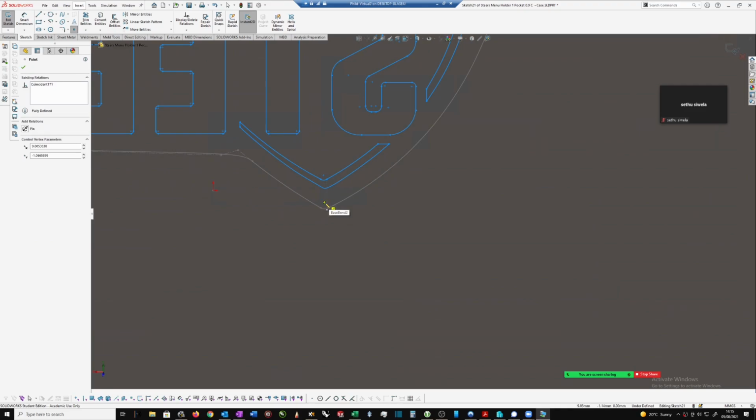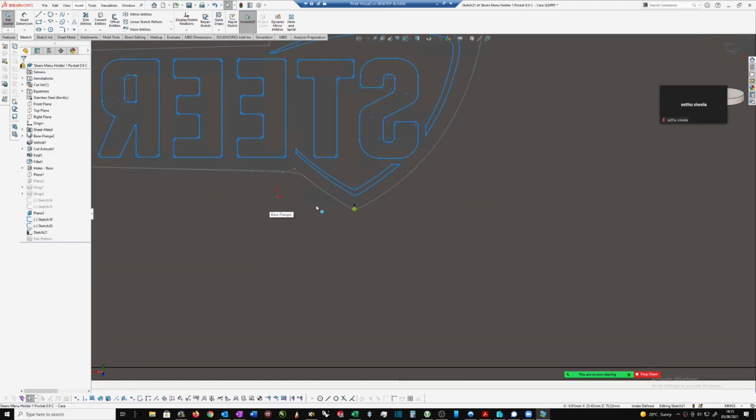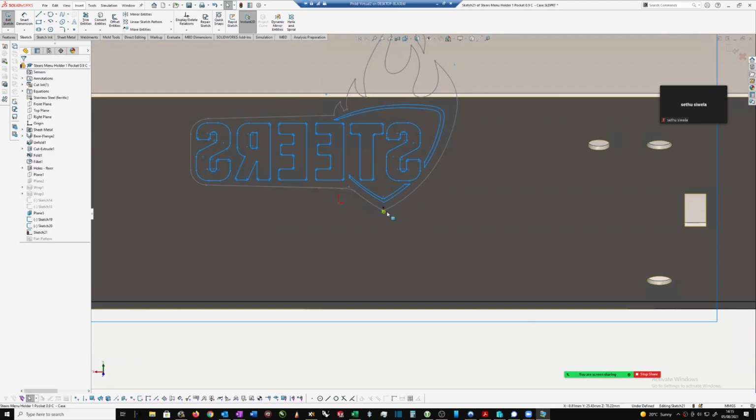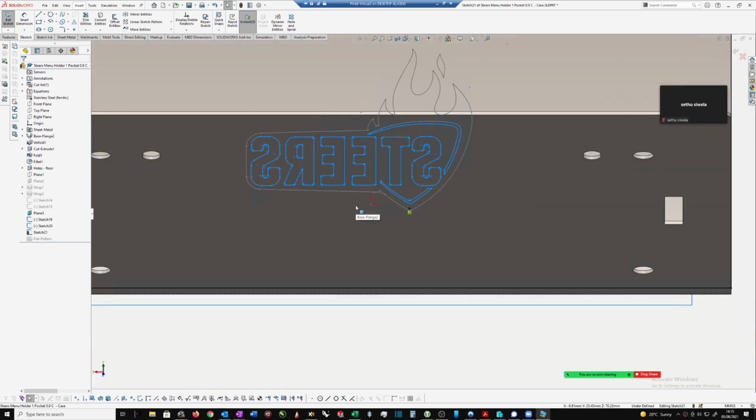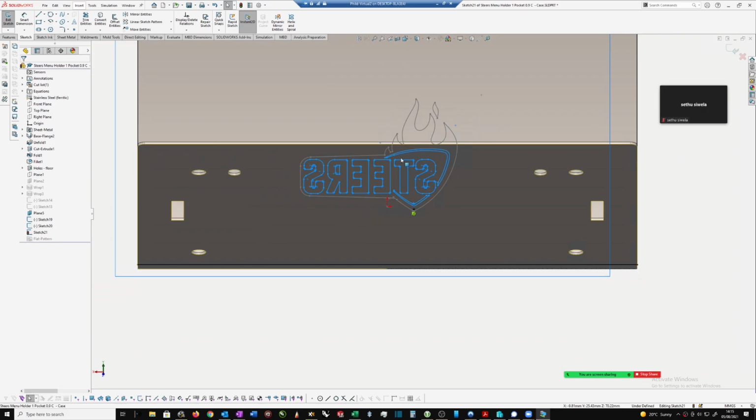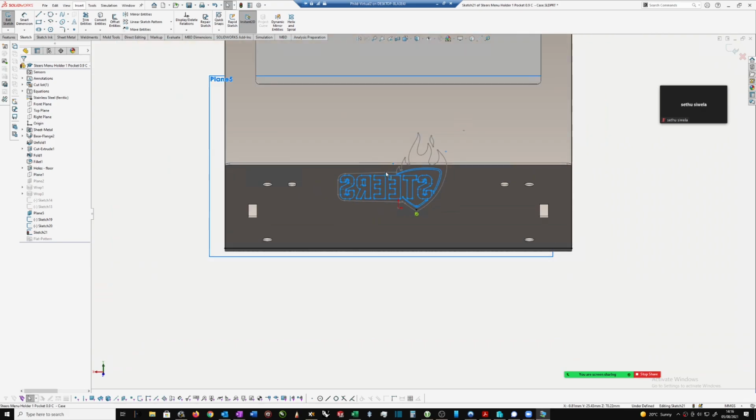And they should now be linked. This point and the one beneath it. I don't think they are. Yes, they are. You can see it's gone black. It means it's coincident with the sketch which lies underneath it. So I've actually got two sketches here. I've got this top sketch and that bottom sketch. I've now uncoupled them, and I want to make this as like one unit.